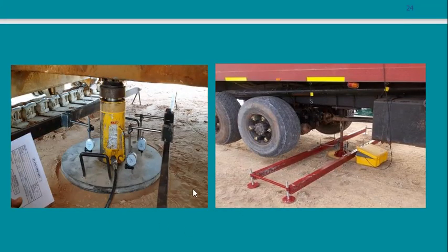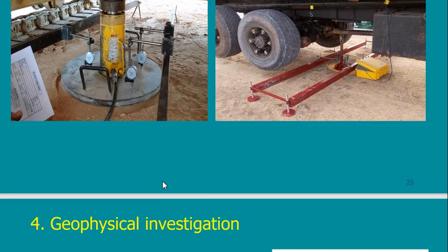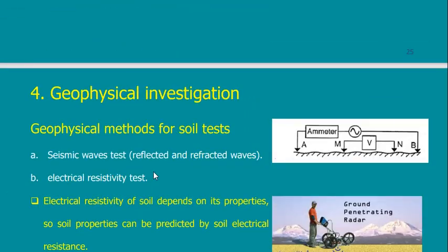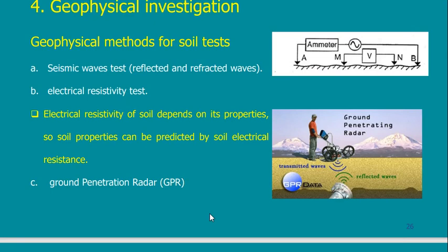There is something called the plate loading test. All of these are tests that are conducted on site. These are very important because tests conducted on site give me accurate values, because the soil is in place, it was not moved, it was not disturbed, so it is very good. Another type is called the geophysical investigation, where something like the ultrasound or the sonar